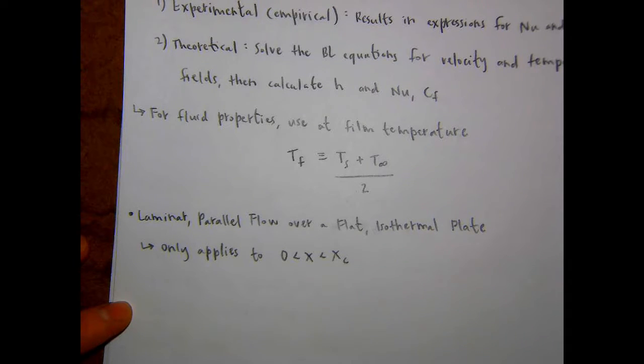So if you're going to work a problem, you would want to first check where the transition to turbulence occurs, and then figure out which regime you're in. And then if you're in laminar, use the laminar equations. If you're in turbulent, use the turbulent equations.